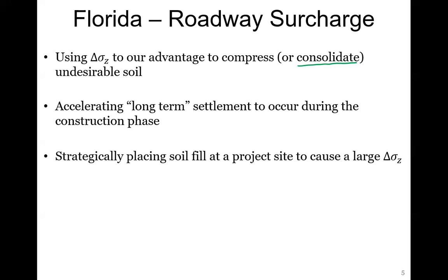Soil is kind of the same way in low permeable soils. If you can picture that water balloon like a big chunk of clay, the pore space in that clay is so small that it has such a low permeability that if we squeeze it for a really long time, eventually it's going to change in volume. That squeezing is basically that delta sigma Z that we need to use. So we see that in organic soils and in clay soils, and that's what that term consolidate means.